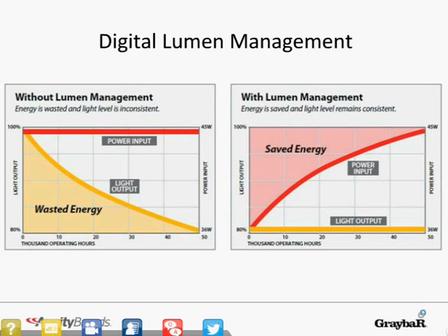With fluorescent fixtures, as you can see on the left-hand side of the screen, lighting designers must take lamp degradation into effect when they're designing a system. That is, they know that the brightness of the fluorescent lamps they put in on day 1 will not be the same brightness as those lamps are at year 5. Therefore, they put in lights that will provide adequate lighting at year 5 when the lamps have degraded. In effect, they're overlighting the space from day 1 to year 5.